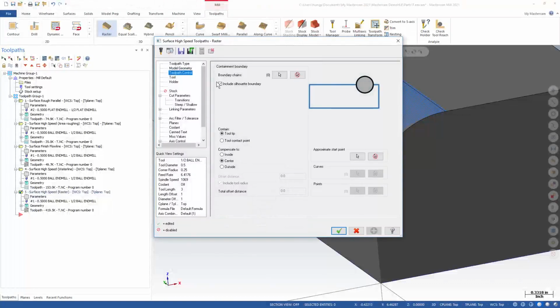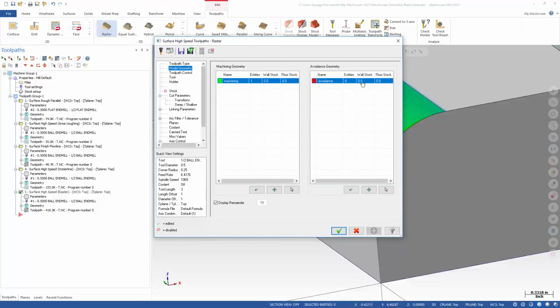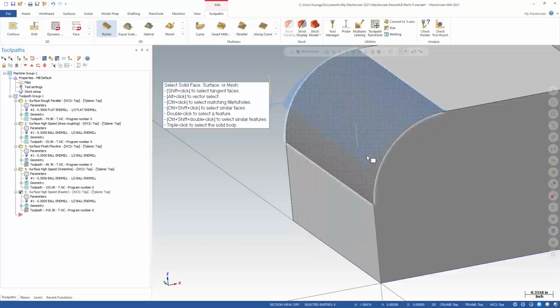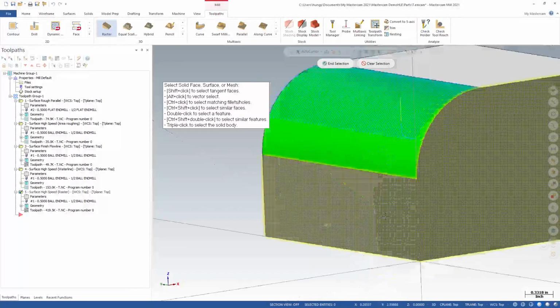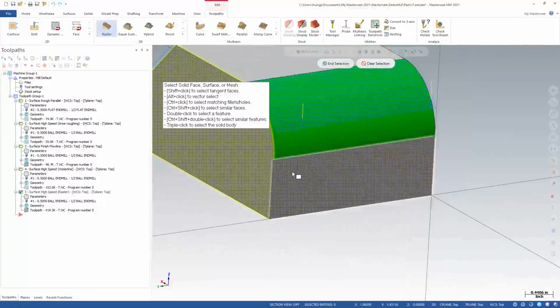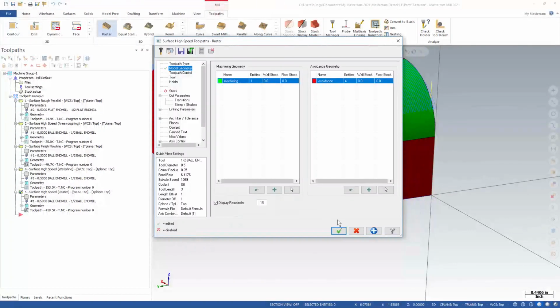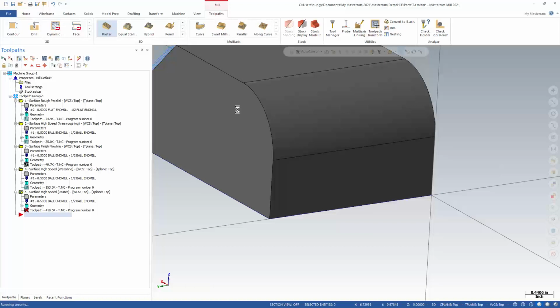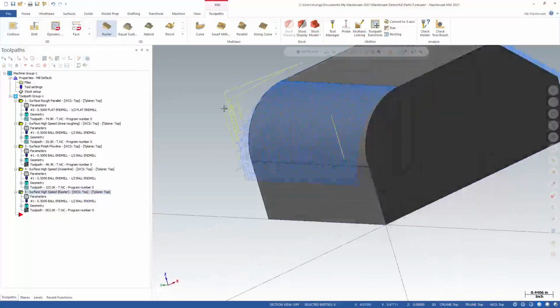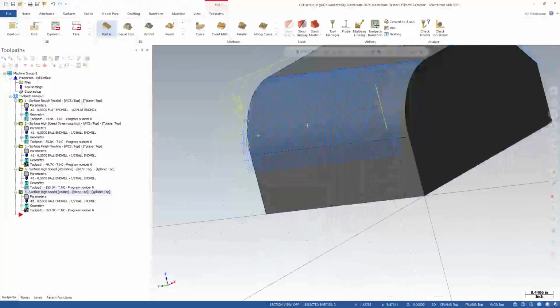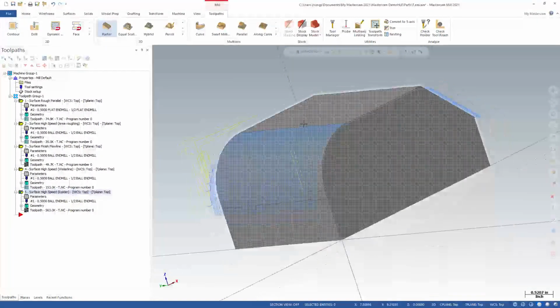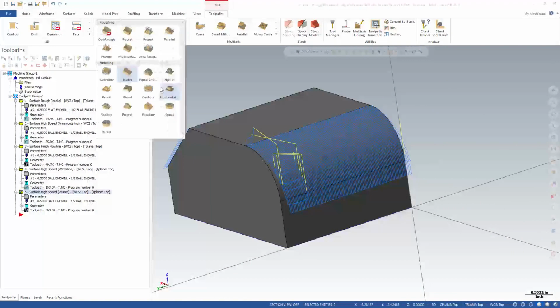To get around it, you do not have to use this. Instead, you click on the avoid surfaces. So you want to avoid this surface, that surface, that surface. You can actually avoid the top as well. Okay, regen. So you can cut this surface. So you can use different combinations of it. For finish, for roughing, you just have to pick the one that is suitable for it. But the majority of them are very similar. One will do a better job than the other.